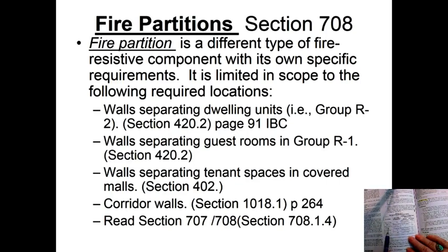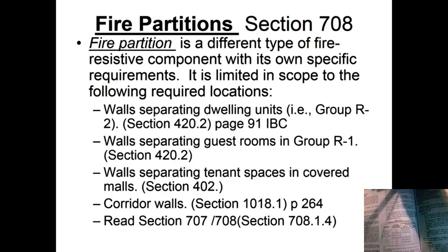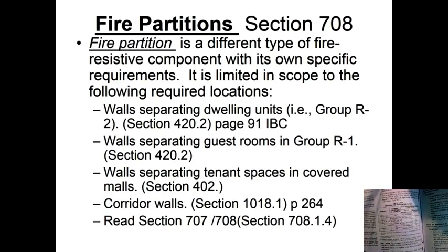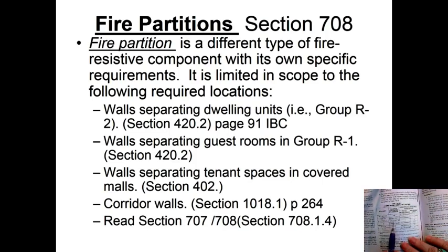So it's telling you that if you have an occupant load out of any of these particular occupancies, assembly, business, educational, remember right here, factory, mercantile, all of these that you see, if there's greater than 30 without a sprinkler system, you have to have one. If you have a sprinkler system, it's none. So every hallway, we want you protected. So if a fire starts down the room and you have to go out down the hall to get out, it's giving you a little time to do that.